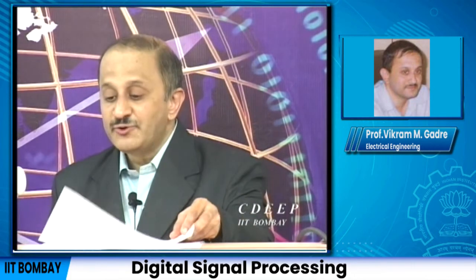And if the impulse response has non-zero samples only for non-negative n, that is n equal to 0 and positive n, then the output at a given point depends only on the input at that point and on points before it, so to speak, points from the past, right. We will come to that a little later.